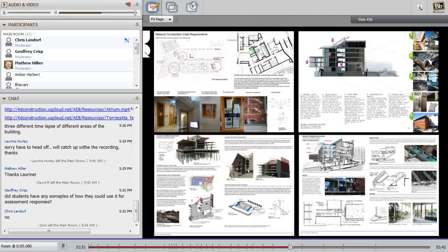Once I had an example, students understood what was required and that it wasn't a trick question. So if we look up the very top here, they're starting to analyse where the fire stairs are in the building and how people are expected to get to them, the sorts of distances between them. They're looking at toilets, those sorts of amenities are a big part of the building code, where fire hydrants are located and the reach of those sorts of fire hose reels around the building.